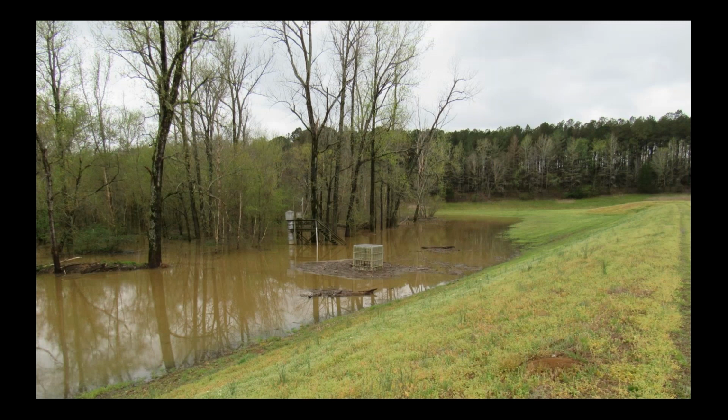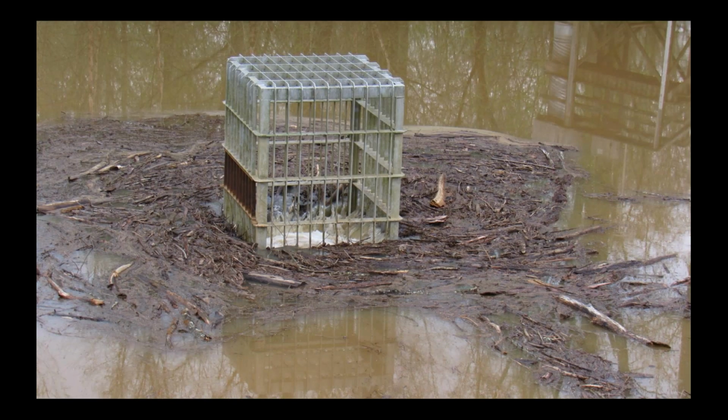Another reason why a dam can be overtopped is because the spillways become clogged. Well, here we have the principal spillway, and it's equipped with a trash rack, which is really important, because the last thing you would want is for the conduit to be clogged. So the trash rack is doing its job here, but this particular trash rack may not be adequate. It could, because of the debris, clog.